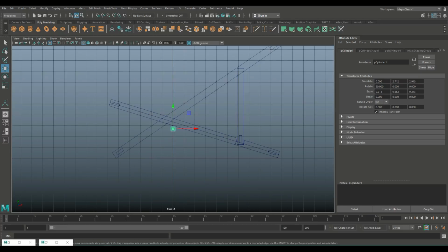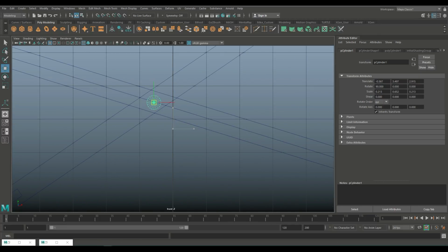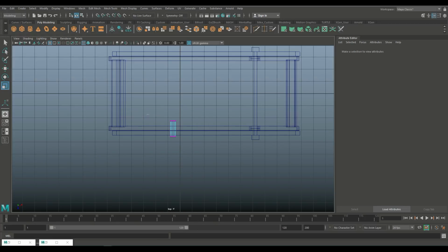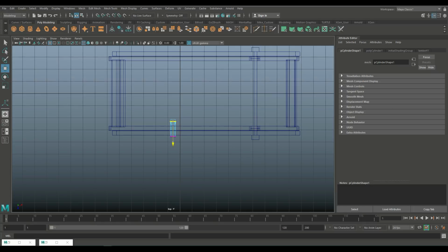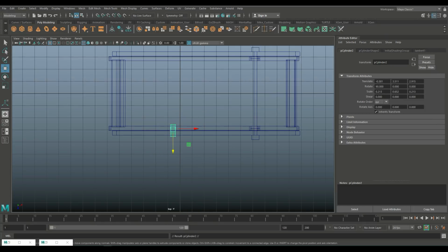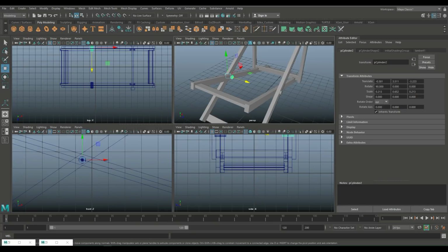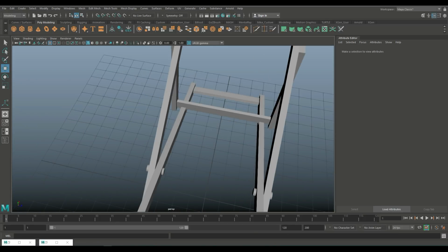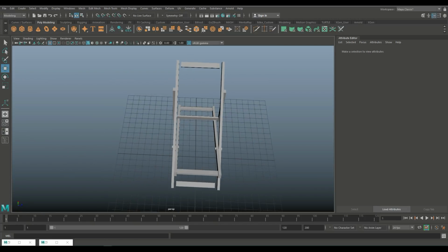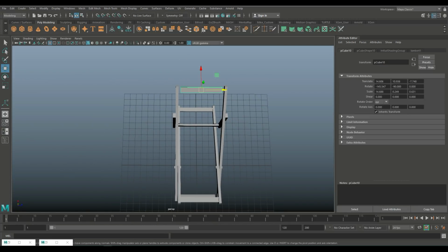Let's go in here after frame. So let's put that in here. If we look from the top, we'll take these vertices, bring that in like this, and then we'll go into object mode, Control E to duplicate, W to move it over. So that should work. So there you have it, yeah. And then let's have a look at our cloth, and this guy needs to be extended a little bit.